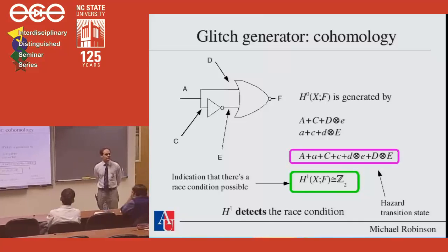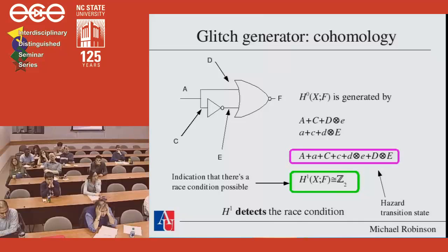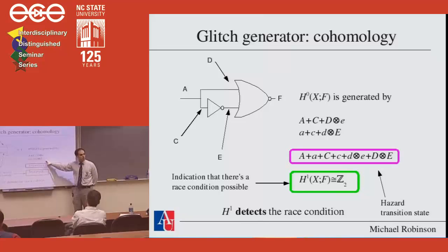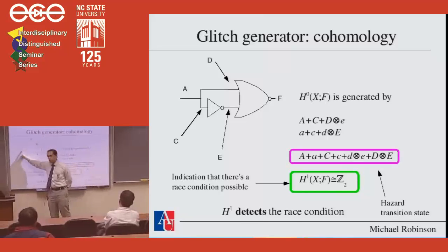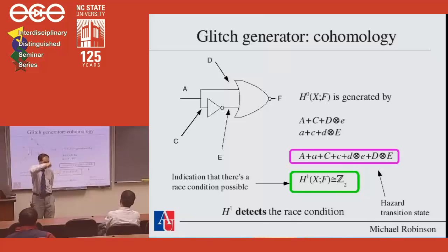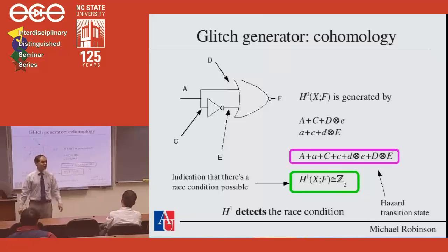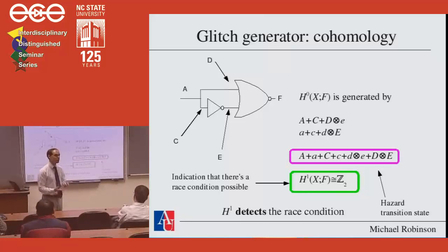And so what does the first cohomology give us? So these particular elements, when you go ahead and do some interpretation on them, take a look at what they seem to correspond to. What that tells you is a logic 1 here on input, and the other one is a logic 0 on input, and they're being held stable. Now there's this additional guy here, which is when you enforce it to be in transition. That is what this global section basis element tells you. Now of course you can take linear combinations of these, but then they're in Z2 coefficients. You don't really find too much else.